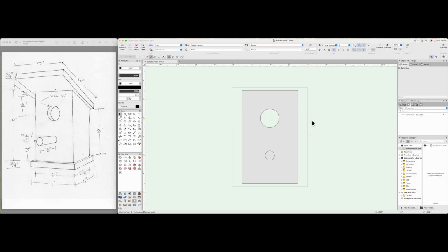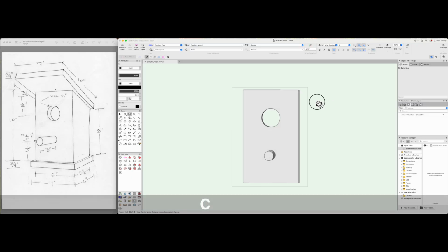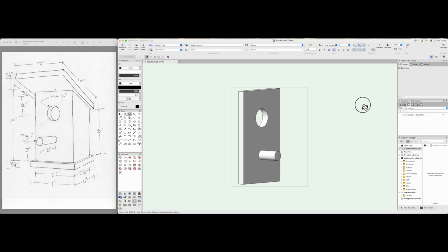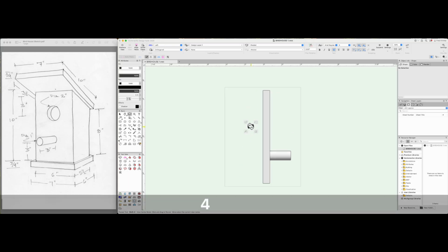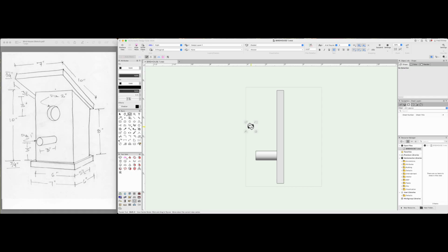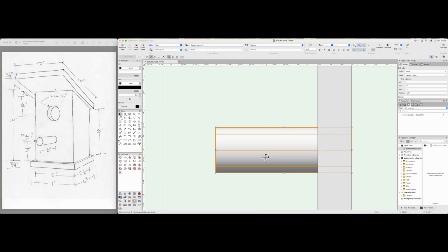All right. If we look at this, and look here, you can see you are now in a 3D world. So what we're going to do with this peg is we are going to pull it out. There's a lot of different ways to do it. I think the best way is using hotkeys on the 10 key. If you hit 4 or 6, you will be looking at the sides. This is the left side and the 6 is the right side. You can see there is our peg.